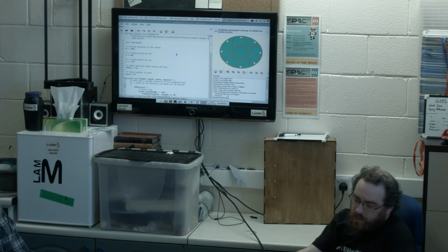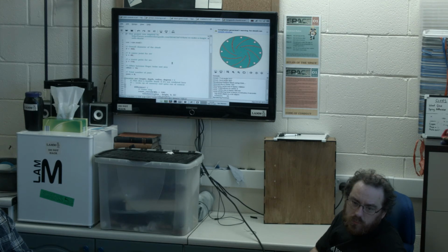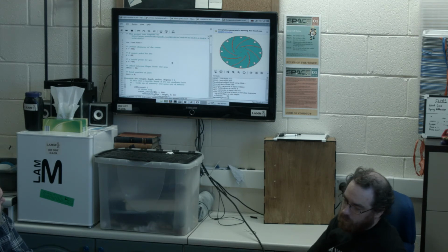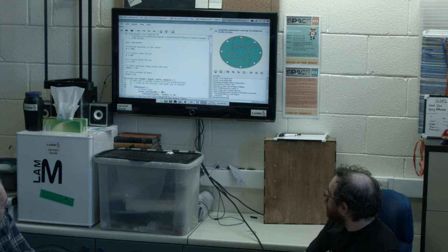Yeah. I haven't found anything like that. Actually, FreeCAD uses a tree model. So everything you do is translated into a tree, and everything branches out. If you do one of those sketches, the sketch will appear in a tree. If you then apply a modifier to it, it will branch out. You click the little plus, like in the folder structure in File Explorer, and you'll see that the sketch is there under the transformation that you did.